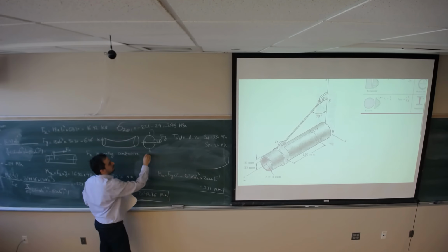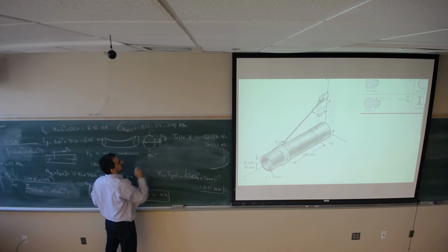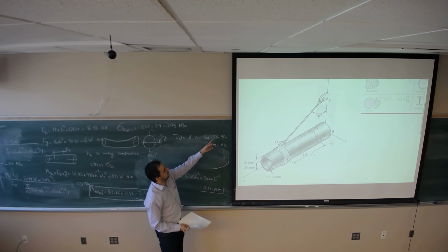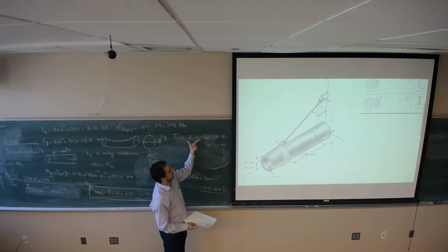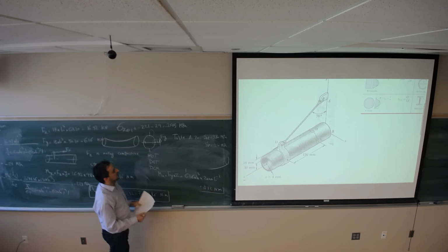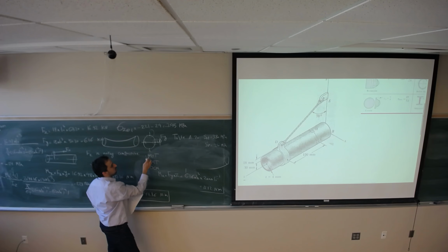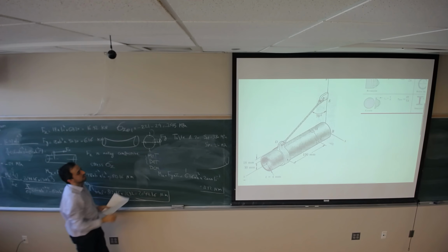The options are maximum shear stress theory, distortion energy theory, and the last one is the ductile flow mode. Since the ultimate strength for tensile and compressive would be the same, we can use either maximum shear stress theory or distortion energy theory.